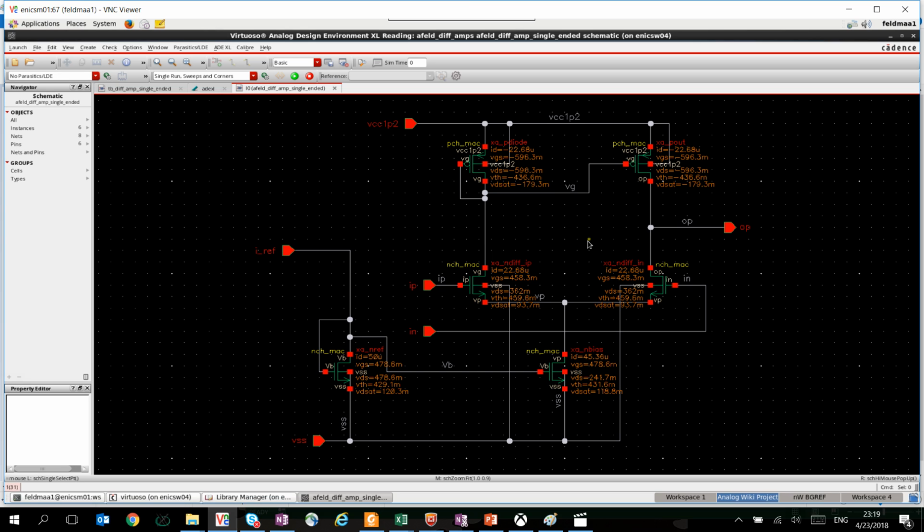So if I would have to evaluate it by small signal, we know that usually the GM of this circuit should be very closely the GM of one of these transistors, either XA diff IP, or XA N diff IN. Usually that would be the GM of the circuit, at least without too much parasitics.